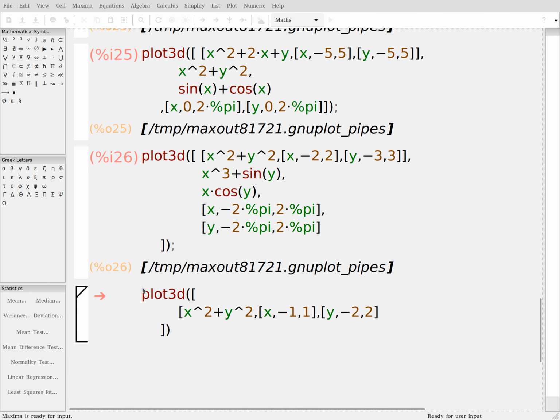That very first line right here has a parentheses and a square bracket that corresponds to the square bracket and parentheses over there. And in the first line here within Plot3D, we have the expression followed by the x range, y range, and keep in mind we have to close that because the entire thing over here corresponds to the first expression.